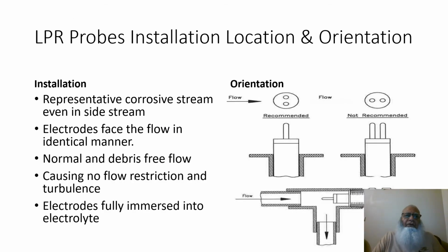This slide shows the LPR probe installation location and orientation. The installation should be done at a place where the fluid stream's corrosive characteristics are more representative.